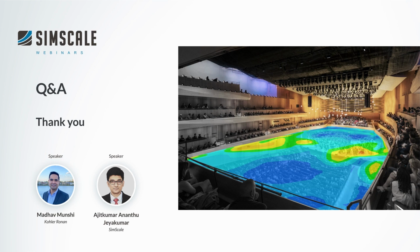For tools like Revit or any other architectural tool, there are options where you can set templates for simulations, and templates for BIM or HVAC or lighting modeling. You can strip down details like doorknobs or sometimes the grills that are not significant for the flow, and keep that as a template for simulations.